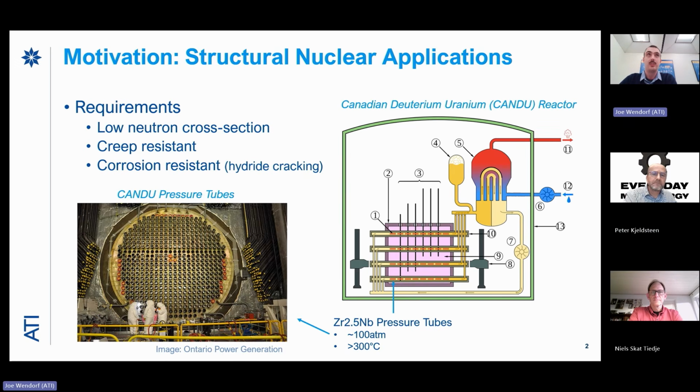So probably the main reason why zirconium alloys are used extensively throughout nuclear reactors is that they are very neutron transparent. So when you have a nuclear fission reaction going on, you have a neutron that hits an isotope called uranium-235 that splits and 3 more neutrons are generated. And running a nuclear reactor is all about making sure that one of those 3 new neutrons triggers another reaction.